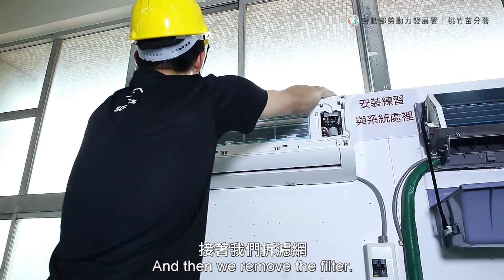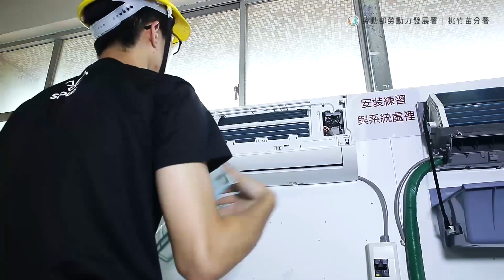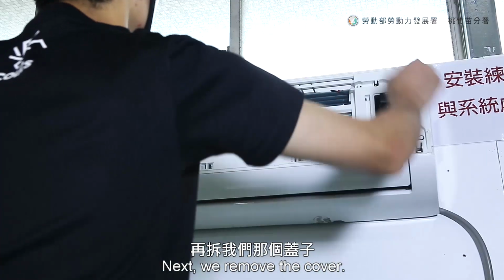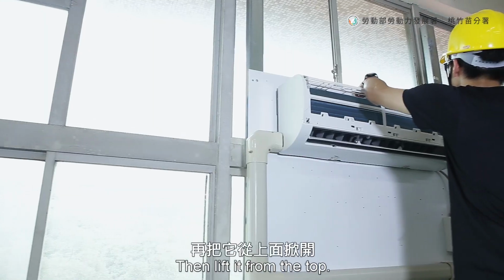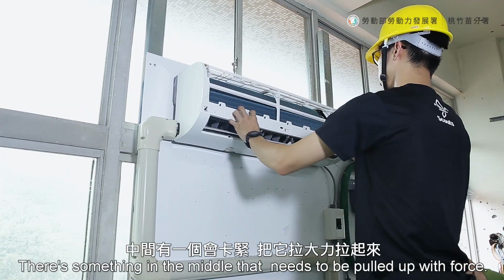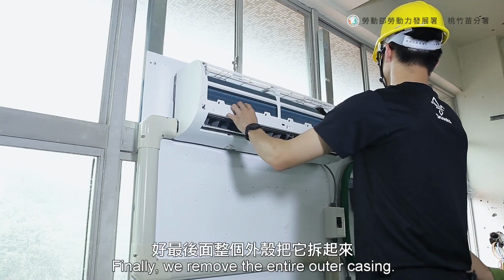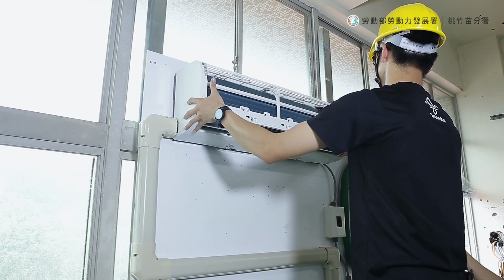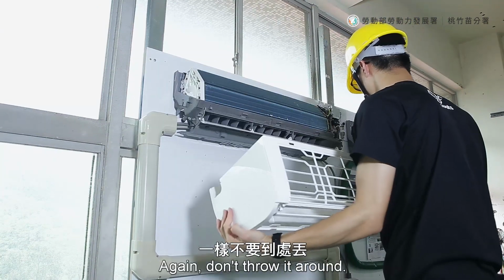And then we remove the filter. If it's dirty, we should clean it. Next, we remove this cover. There are 2 clips on the cover that need to be detached first, then lifted from the top. There's something in the middle that needs to be pulled up with force. Be careful not to break it. Finally, we remove the entire outer casing. Again, don't throw it around.